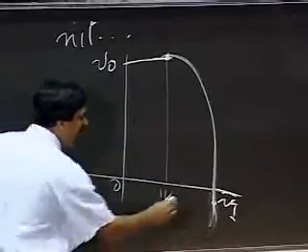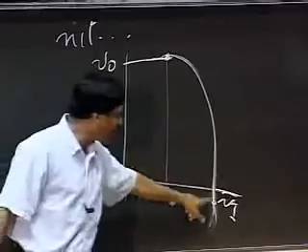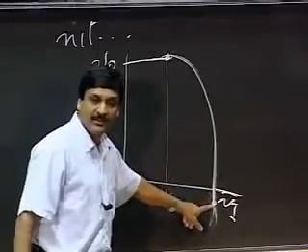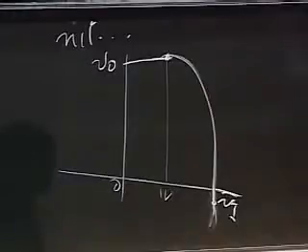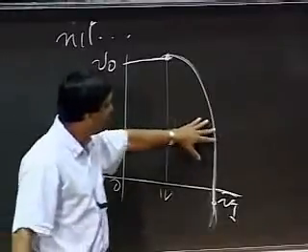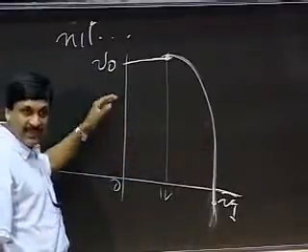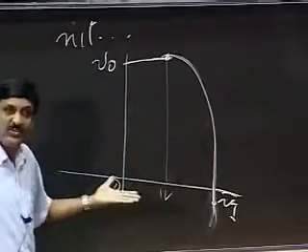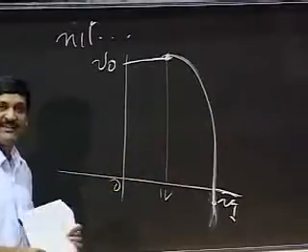A point down here says that the output has gone negative. This is 0 here. The output has gone negative, and my current source is still supplying a current. Up here, the voltage across the device, V0, is positive, and it's supplying a current, so it's consuming power. It's burning power like a resistor, like all bad little resistors do.